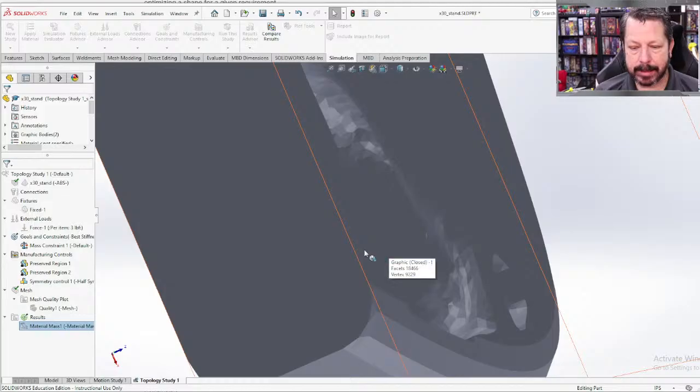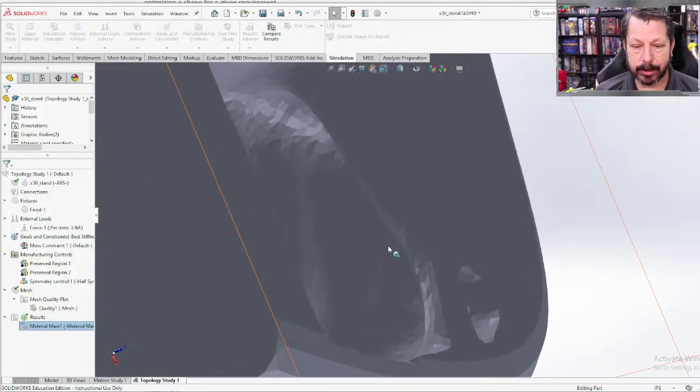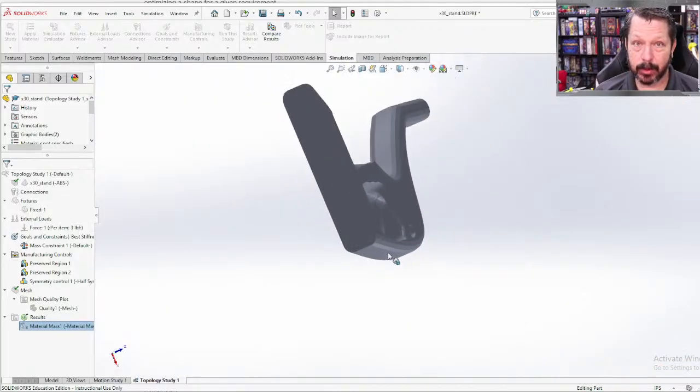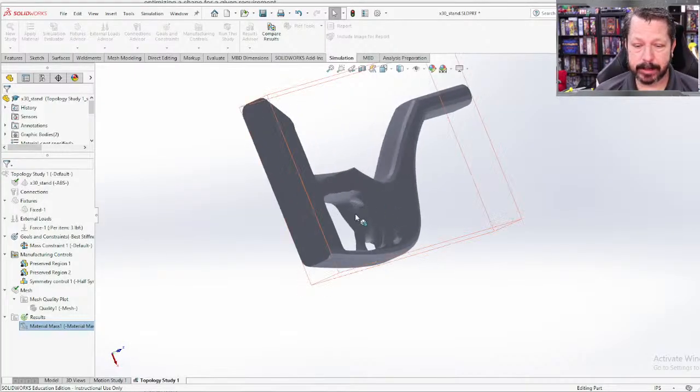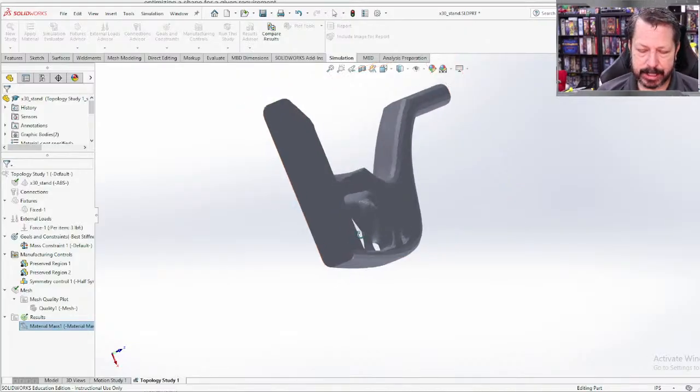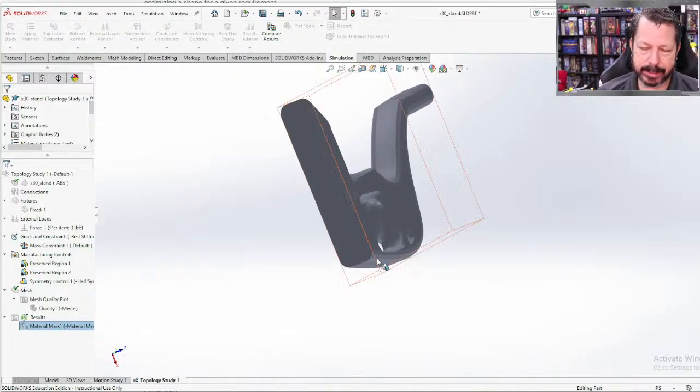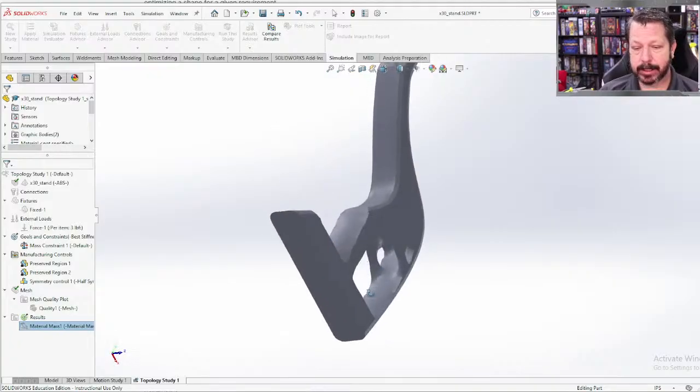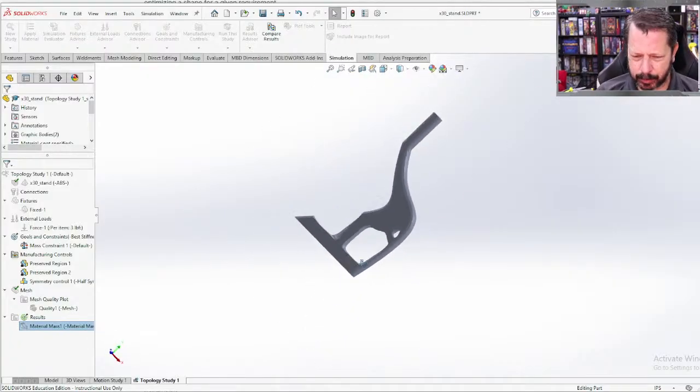So that would make this particular thing actually kind of hard to machine, right? Or to mold in any way, because you'd have to have some removable core if you're molding or casting this. And to machine it, you'd have to have a 6-axis robotic arm with a long mill bit to get up in there. But 3D printing, we can probably do that relatively easily.